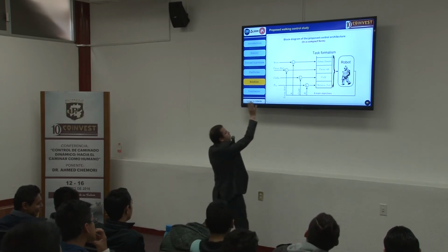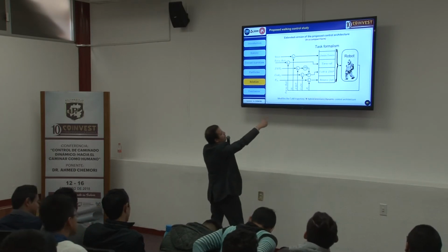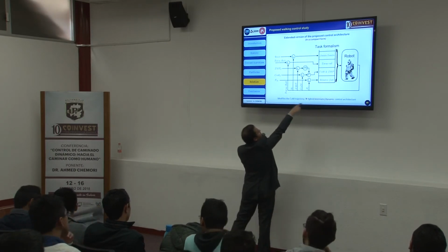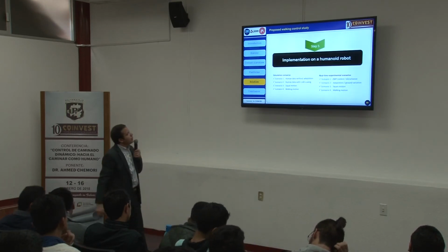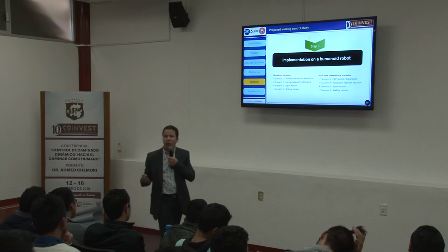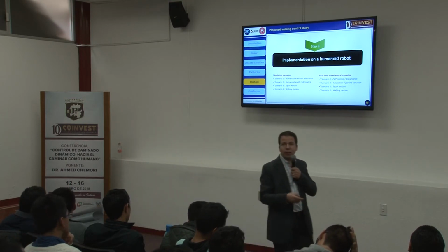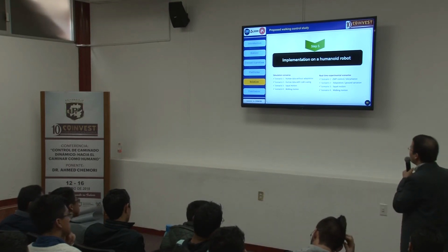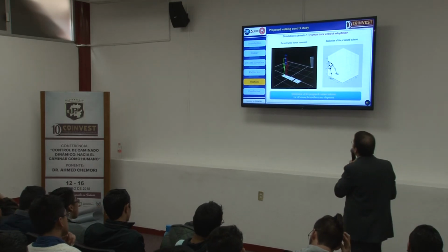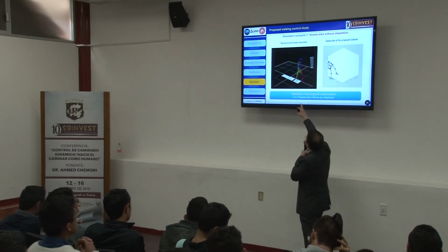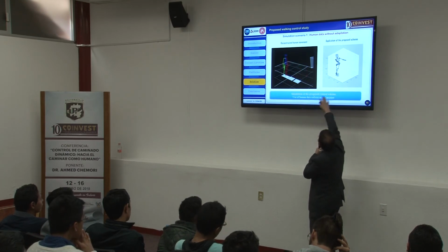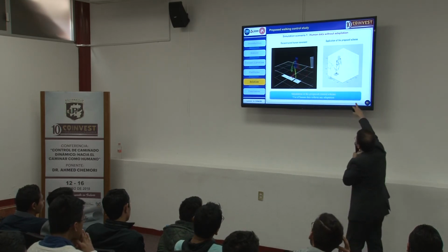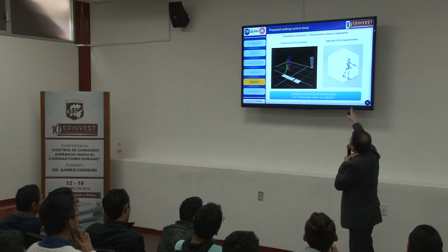This is the task form, the kinematic control, and for the dynamic control we add here, as you can see, a closed loop for the ZMP for the dynamic walking, and we arrive here to the implementation. So we have tested this controller on different robots, and I will show you some results. Here, as you can see, just a simulation. It's the human walking. First of all, we have tried the data coming from the human directly on the robot without any scaling. And look here the difference.